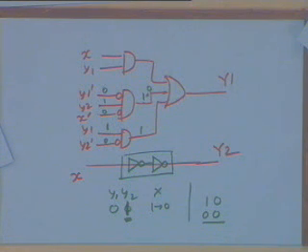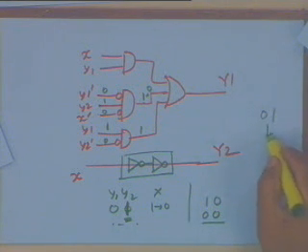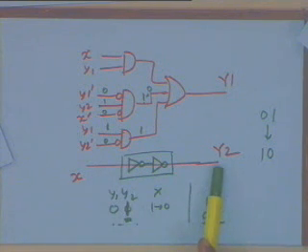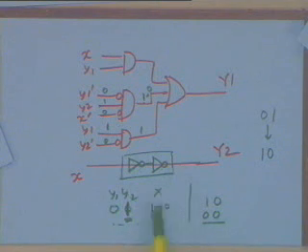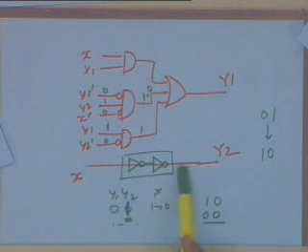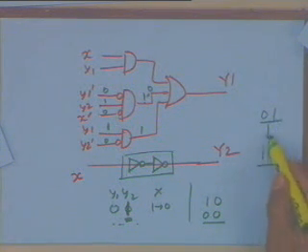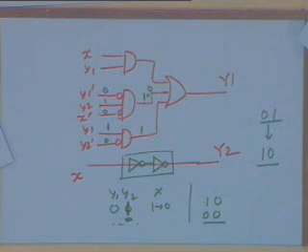The problem has come because of the fact that I expected 0 1 to change to 1 0. The source of the problem is not just the fact that I don't have a delay over here. That's not really the problem. We can introduce the delay, but the problem is how do I introduce the delay to make sure that it actually will wait till that change occurs. I am not going to count the delays on each path or for each transition, I am not going to keep on computing my delays. So the source of the problem is I wanted a state change which involved not change of one variable but change of two variables.